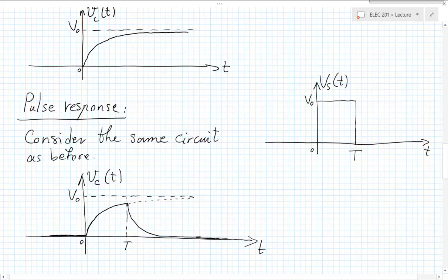Okay? So this is actually a very good question, because this is the kind of thing that one could easily get confused about. Before time t, the capacitor voltage was growing, and it was looking at eventually saturating to V naught. At time t, the conditions changed, and now immediately it will reverse its trend. It will start decaying. But it has not changed its value instantaneously, right? So there is no sudden jump in its value. There is no discontinuity in its value. But changing the trend immediately is no problem at all.